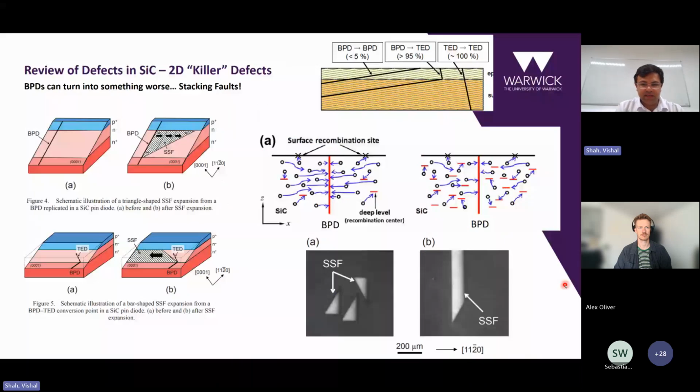The other important point in silicon carbide is that a particular type of defect, the BPD, which is in the basal plane, during device operation, if a lot of carriers get into that defect, they can recombine. And when they recombine, they can actually expand that one-dimensional defect into a two-dimensional defect, which becomes a killer. So it completely destroys the device action within your device. So being able to control and detect BPDs has been quite a big exercise for the last 5 years.